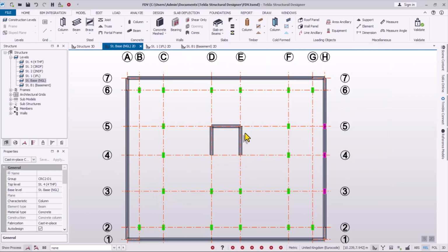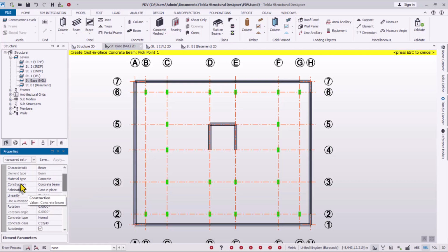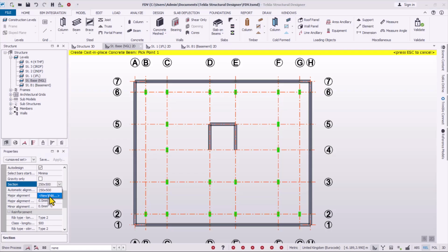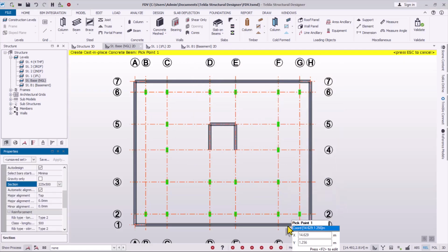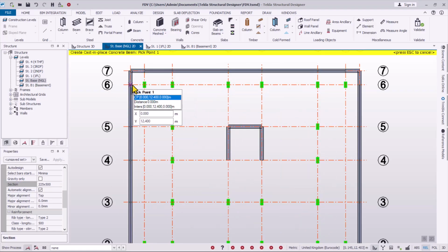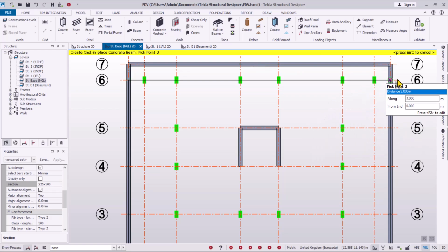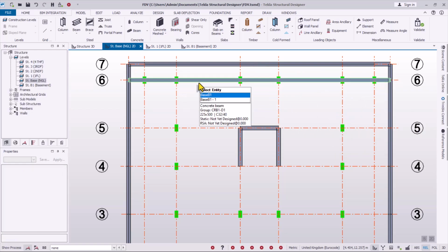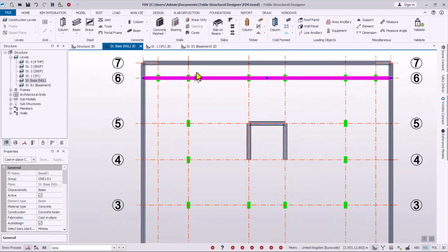We have a beam connecting all of these provisions. So click on the beam right here. So we scroll down, see the materials and the beam properties. Let's check the sections. So we are going to be having 225 beams from here, 225 by 500. Click on the OK option. All right. So now we want to be creating beams that will connect this point. So pick the first point. You can pick it all through to have it placed, but if you select it, you can see it is actually a single beam, a continuous beam is being placed successfully. All right, this is good.